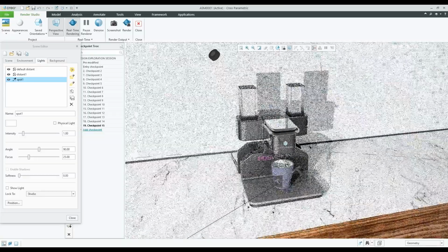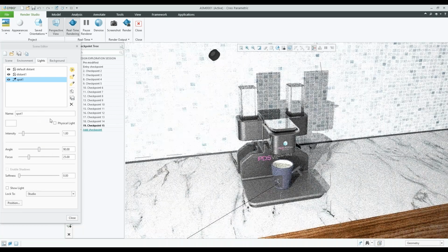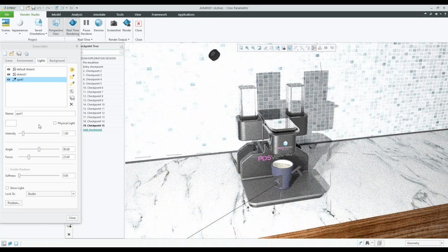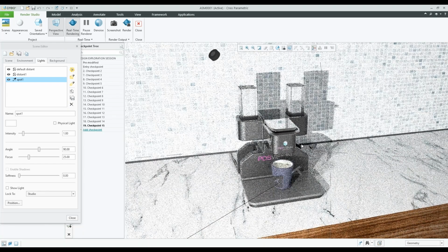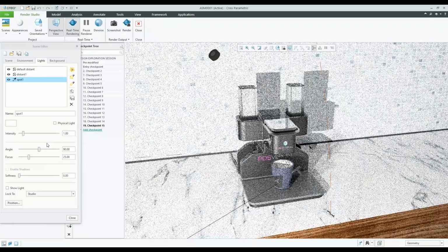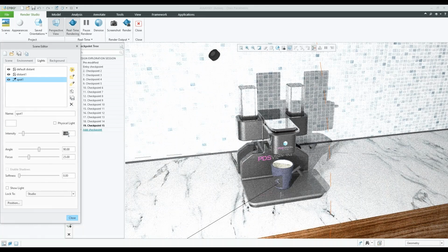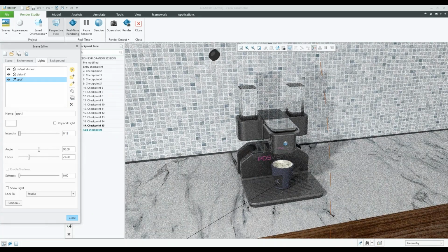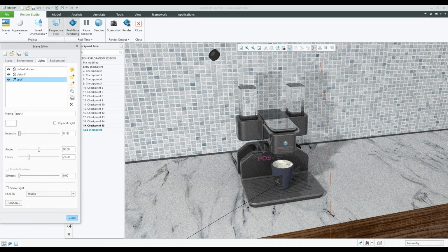And you can see here that you can adjust the intensity of the light. So in this case, we have an intensity of 1, right? So we're not completely locked into that. You can see it's so bright that it's just kind of blowing out the scene. It's just overwhelming. So I can change that, for example, to like 0.125 or something. And now that's a lot softer. Now we're not getting a scene that's completely blown out with this bright lighting. It looks a lot better. We have that shadow cast.